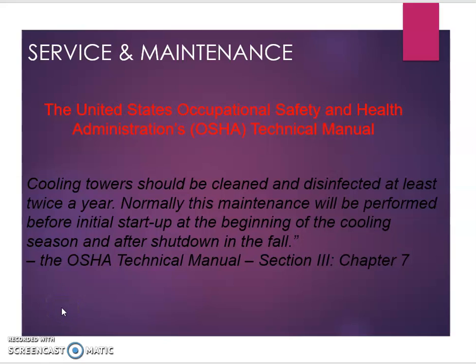Based on the recommendation by the United States Occupational Safety and Health Administration, OSHA Technical Manual, Chapter 7, Section 3, the cooling tower should be cleaned and disinfected at least twice a year.